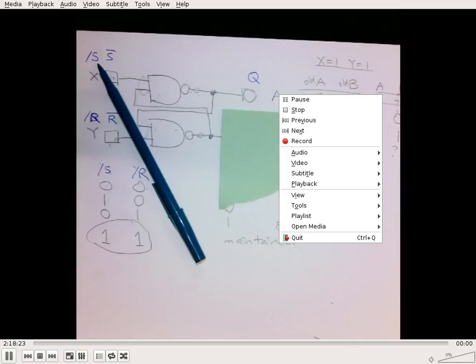The reset of the entire computer is usually active low, which means, for those of you who really looked into the circuit board, there's one particular trace that is called a reset line, and it's universal to the entire circuit board. It is an active low signal, which means if you use a voltmeter and you measure a high voltage, it means do not reset. The moment you ground that signal, you connect it to 0 volt, your entire circuit board resets. And there are reasons why certain signals, other than this one, are active low.